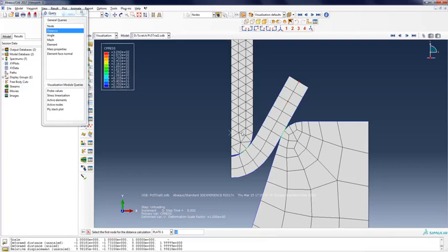You can modify your indentation depth, taking into account that the curvature would reduce the actual level that's needed to create a 90 degree angle, and play around and then come up with the optimal distance of indentation, such that eventually, after the spring back, you get a perfect 90 degree angle. So this will be an interesting study, so that you don't have to repeat a lot of experiments and you do the simulation and then you validate eventually on actual experiment.